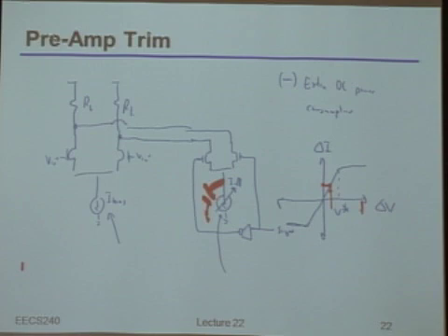That's how offset works. No, that's correct, but remember, it's not that I'm actually adding things directly at the input. I'm first taking the input voltage, going through the GM, as Rachel said, and then adding a current to its output. So in order to get back to the input, I have to go through the reverse of this transfer function. And because of that, the range of offset you can actually cancel here is basically limited by that V star.